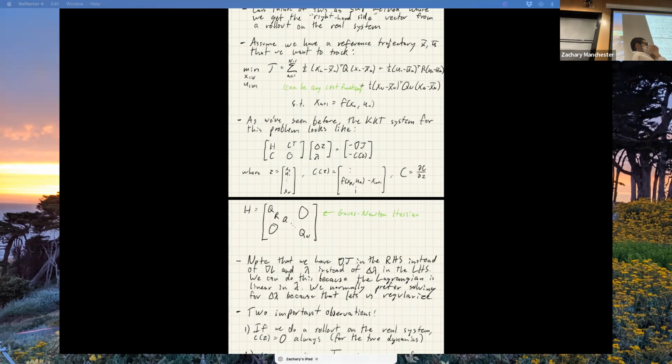So normally I have this model f of x, and I'm using that f of x to compute the right-hand side, and I'm using it to compute the left-hand side. What I'm saying now is, if I do that and I get an answer, cool, I go run it on the real hardware, and now I replace the right-hand side vector with the real data from the real system, but the left-hand side of that equation stays the same and is computed using the nominal model, the mathematical model that you had before. Does that make sense to everybody? Okay. Any other questions about the basic idea?